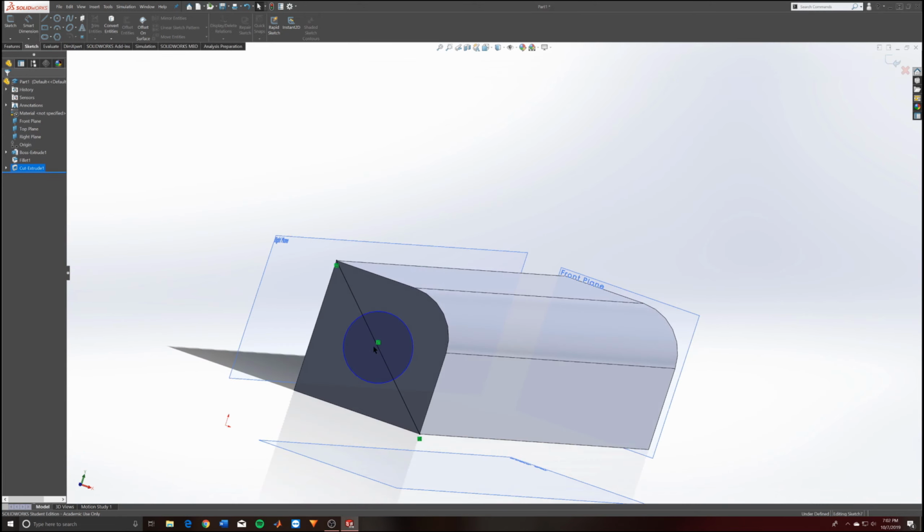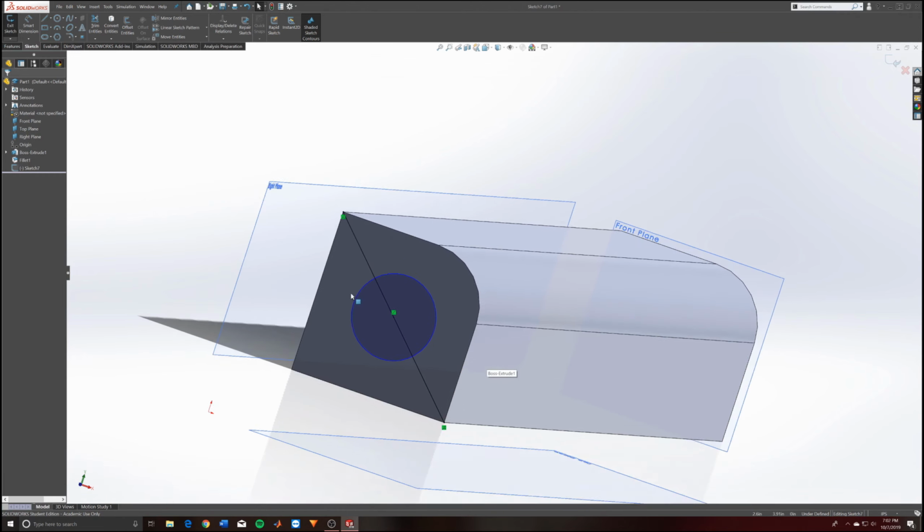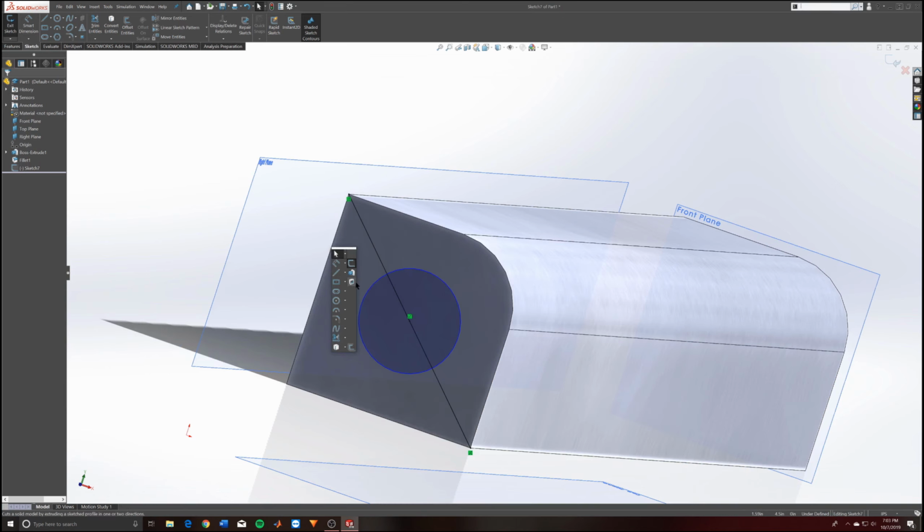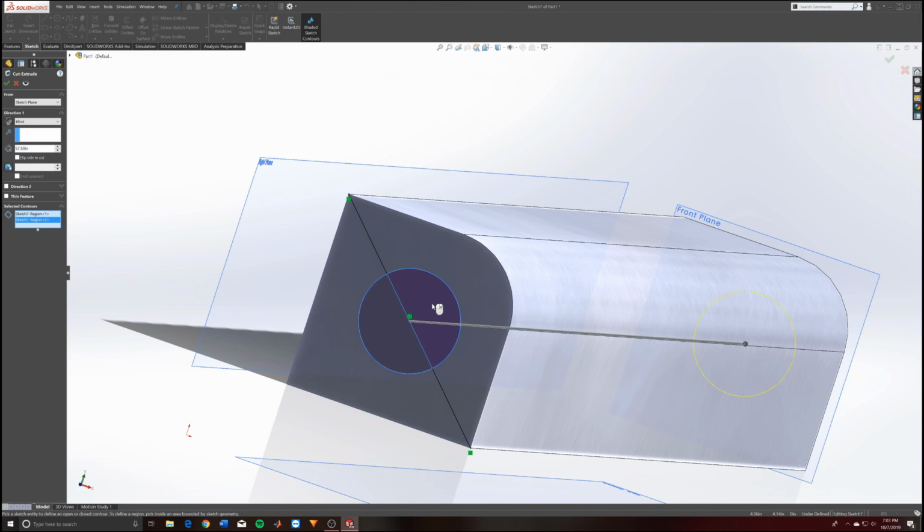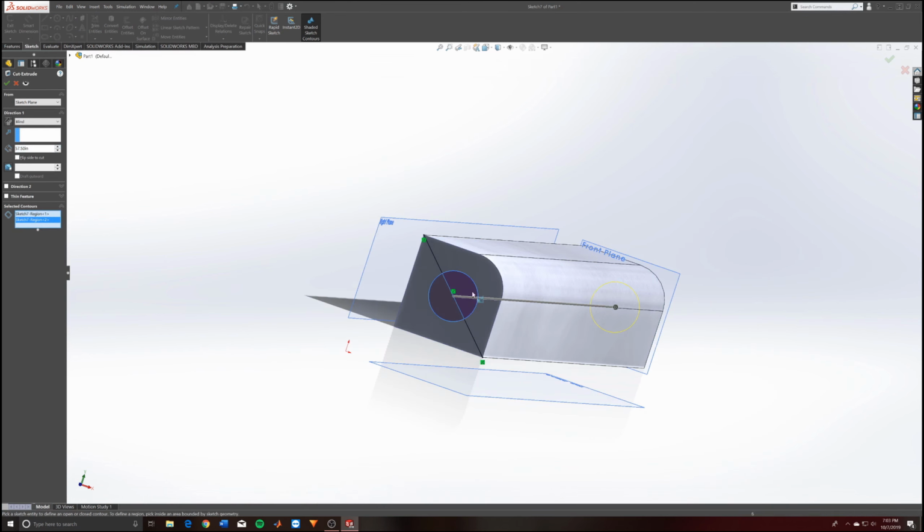And to step back and show you again how I did that, I used my shortcuts, because that's how I usually design, using the S key. I even assigned my extrude boss and extrude cut directly into the sketch menu, so then I can go directly from a sketch here, extrude cut, and cut a hole through this.